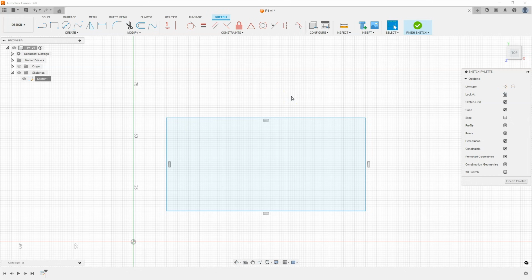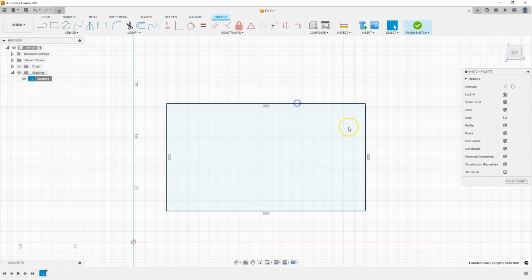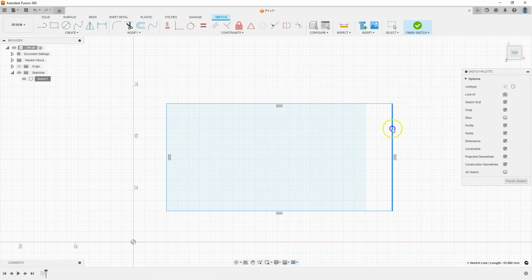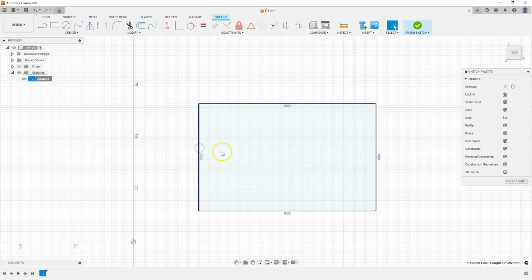And at this point, this sketch has no specific dimensions and no specific location. If you left-click on the geometry, you can freely change the dimensions and positions of the geometry. And when creating 3D models in 3D CAD systems, we usually want the geometries to have precisely defined dimensions and locations. First, let's define the dimensions of this sketch, but now this geometry is selected, so left-click outside the geometry to deselect all geometries.